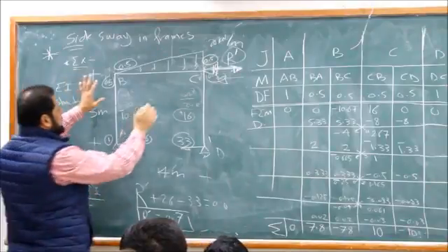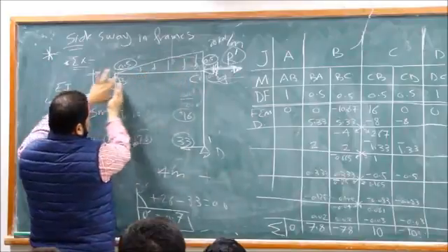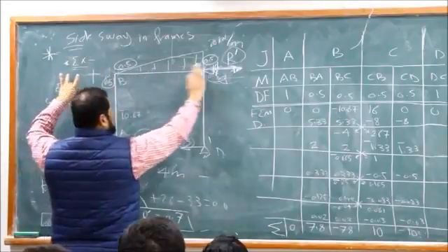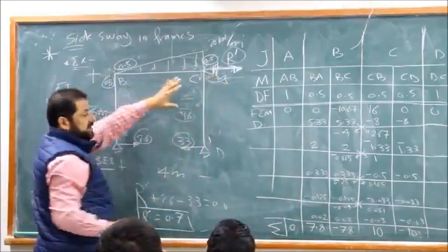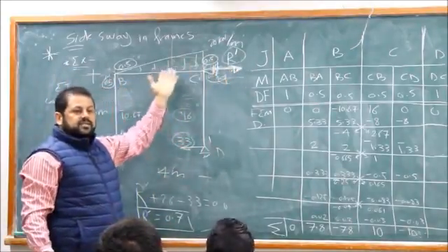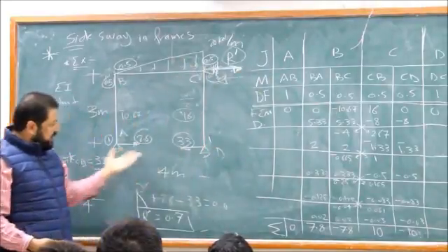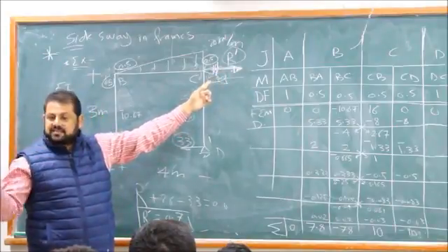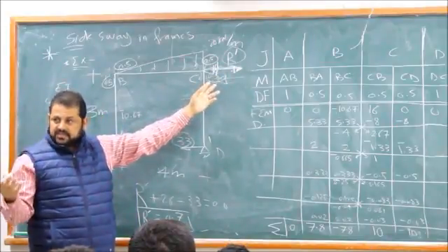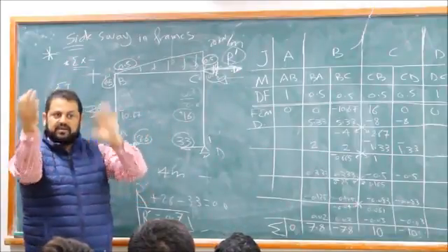Good. So according to this, we realize that this load will cause the sway this way. So to hold it, we hold it this way. So when we apply the load on the frame, to prevent this sway, we develop a reaction to the right. This is the calculation of 0.7. This 0.7 does not exist. So we have to apply a counterbalance to this one, 0.7 in the other direction.